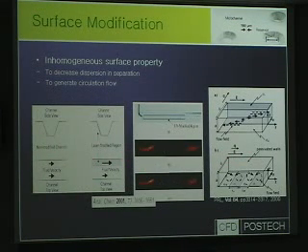And in fact, many people use modified surface property. So by changing the zeta potential at the surface, they could reduce the dispersion, and they could generate this kind of shear flow, and they could make a circulating flow. Actually, this kind of idea was already available.